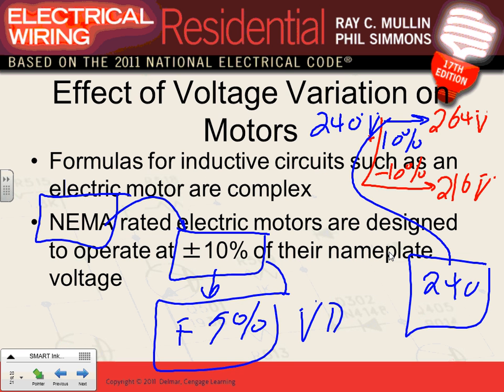Double the voltage on the equipment, you burn it instantly, right? Go 50% on it, you also burn it instantly. Go 25, you cut its life probably by half. So the higher you go in the equipment or the lower, the more you cut its life by a certain value. Any questions about the variation of voltage? Can I have thumbs up? That, Chad, we know that the voltage does not stay constant and varies.